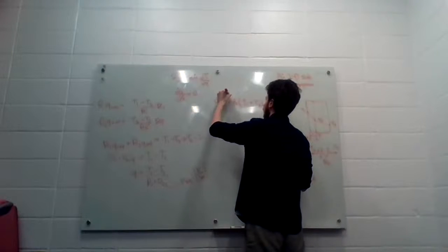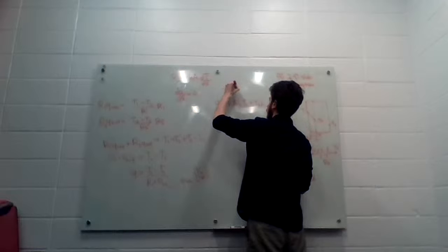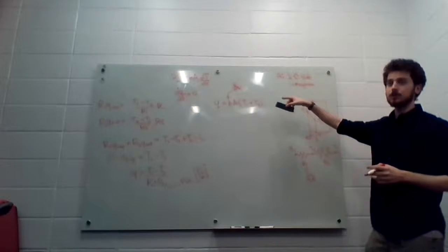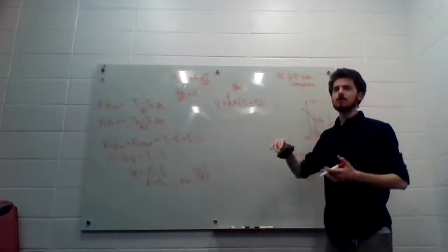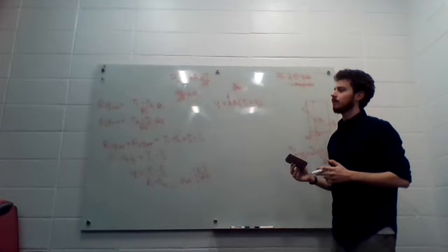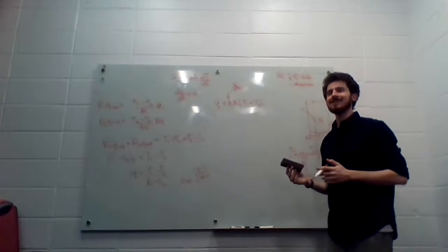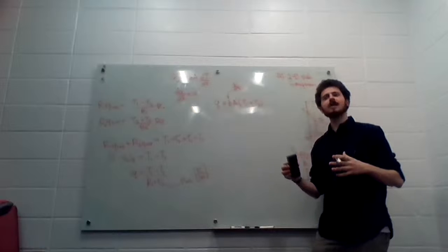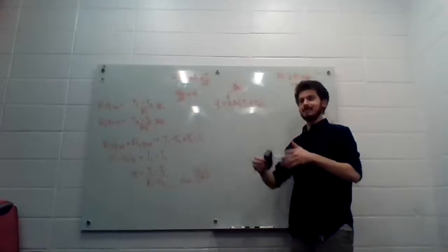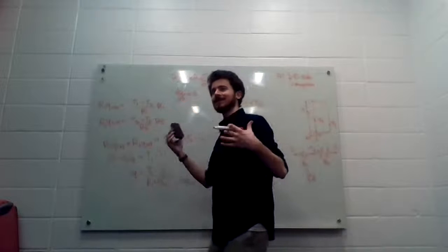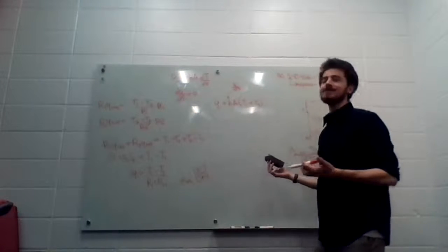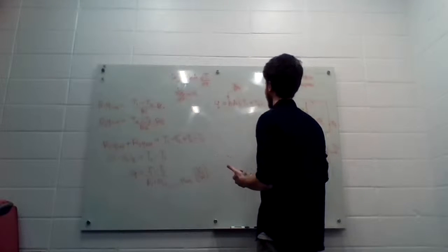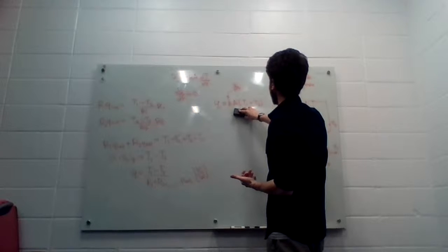H is in watts per meter squared Kelvin. I will say that heat transfer coefficients for convection, which you typically use when you're describing convection, are incredibly enigmatic and inconsistent. There are all these incredibly complicated models where, if you've got a room of a given size, you can say the average internal heat transfer coefficient is 6, but it could be 20. It's the reason that thermofluid scientists still have jobs, because it's really hard to just simplify, pick a number, and have it actually apply.